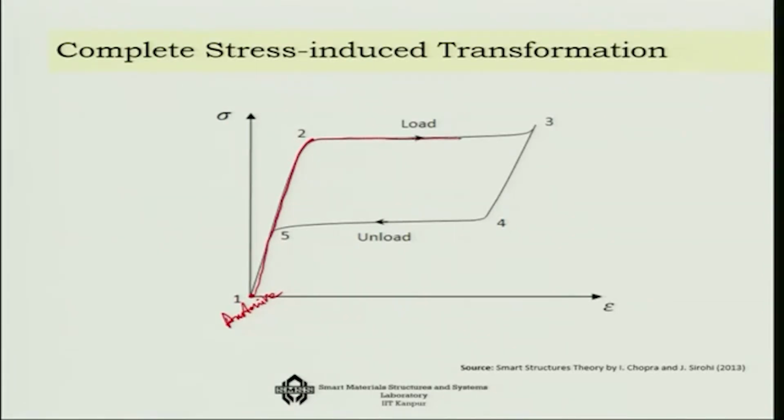This is stress induced phase transformation, and I am going back to the martensite phase, and then from that phase I am reducing the load again, and if I reduce it, initially it is once again elastic, and then the huge change, and it comes back to number 5, and then if you further reduce it, it will be at that austenite state itself.